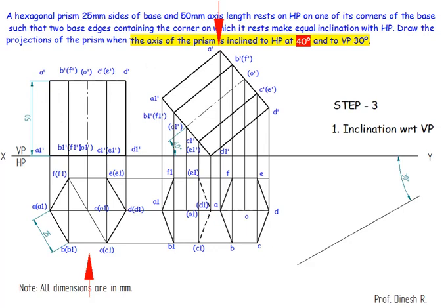So I'll go for arc by center point from anywhere on this point. Make sure that if I'm going to keep O, you have sufficient space and it should not even touch the XY line. So from here I can just keep it here, O point, so D will be here, somewhat E and F will be here.